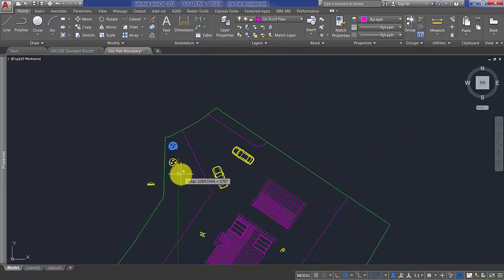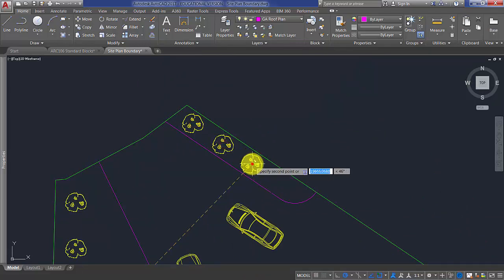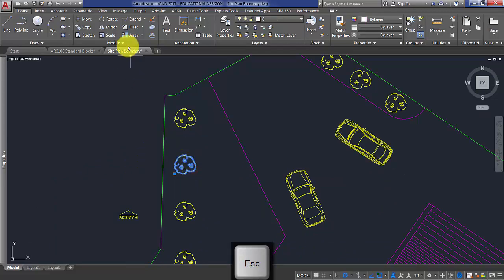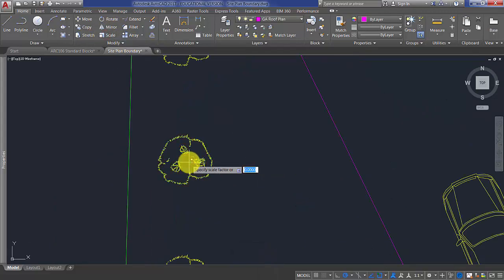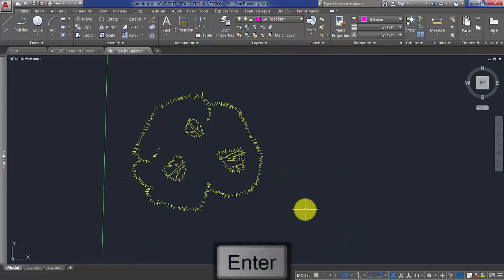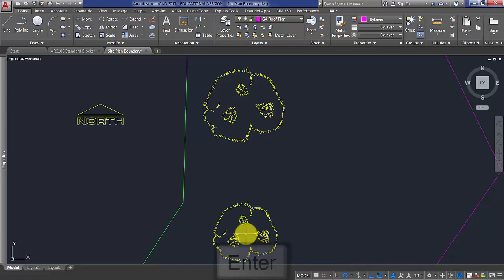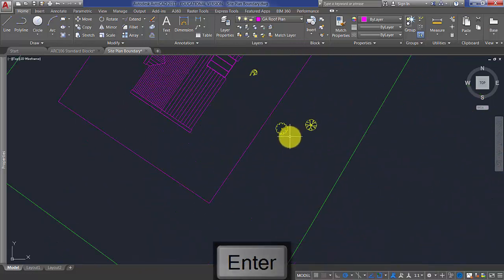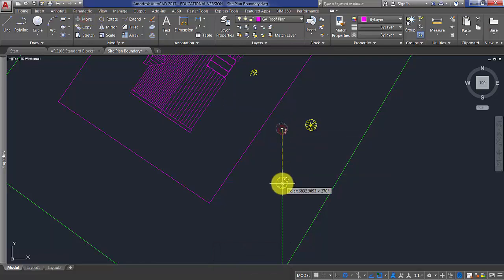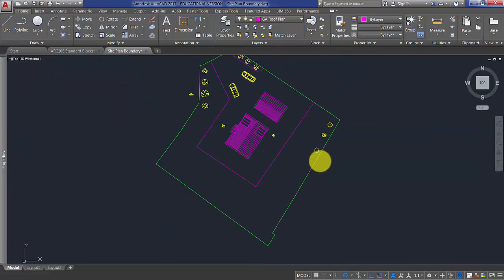Copy that out a number of times. That's picking up a slightly awkward endpoint just there, so let's do something like this. And what you can do is maybe change the scale of those slightly, so let's make that one 1.2, just a little bit bigger. This one again, a little bigger, we'll make it 1.5, just so the sizes look a little bit different. And this one, let's scale it by 1.2 again. And the trees then, those can maybe be alternated down the back of the site, or hedges can be put in, or whatever. Again, different scale sizes and things like that would be good.